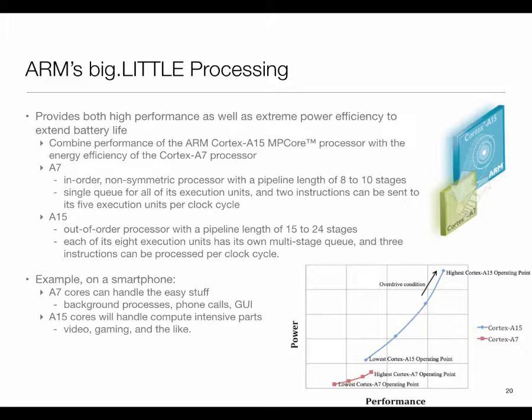Right. So let's say you have an assembly program. In-order means that the instructions are executed in the same order. Now, oftentimes the instruction ordering may be over-constrained, in the sense that I could run a subsequent instruction before or together with a previous instruction, if there is no data dependency among them. So if you have adequate hardware support, you can do this processing in an out-of-order sequence if the hardware thinks that would lead to more efficient usage, for example.